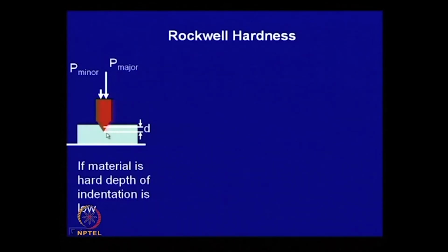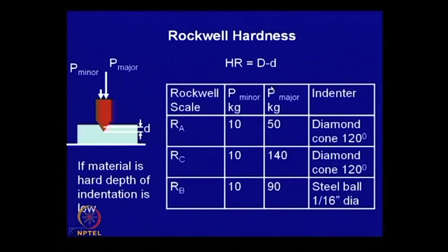That means, the higher the depth of penetration or depth of indentation, the lower is the hardness, and this Rockwell hardness number is something like capital D minus small d. This capital D is some constant depending on the scale that you use, minus d. So, it is a linear function of this depth of penetration, and depending on the choice of